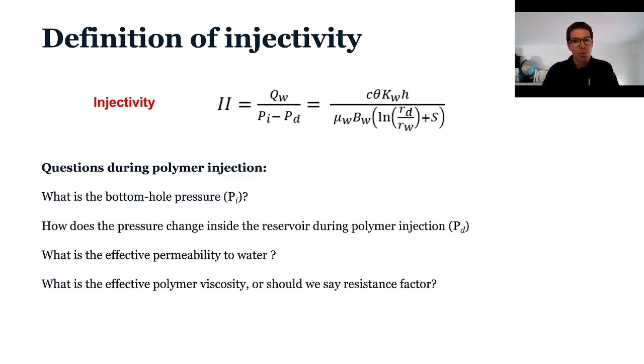What is the real in situ polymer viscosity? Because in the laboratory what we have are viscosity curves, but this will not be exactly the same values in the porous medium between viscosity in the rheometer and in situ viscosity, because you have retention, you have changes of permeability, of saturation of fluids. So this is not considered and will have an impact also very much on the effective in situ viscosity and of course the pressure buildup and the oil recovery.